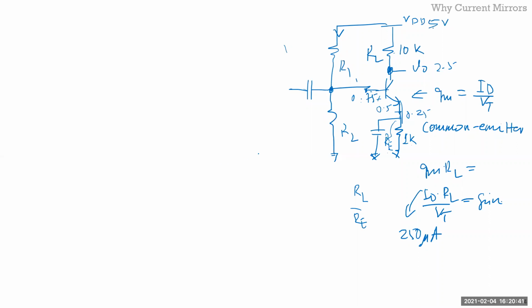And same thing about the capacitors too, right? So these capacitors, if you use them for low frequency, they're huge, right? They're in nanofarads or picofarads. And you're talking about, in 0.18, I think it's roughly about 8 femtofarad per micrometer square. That's gate cap. That's like the highest cap density is the gate cap.